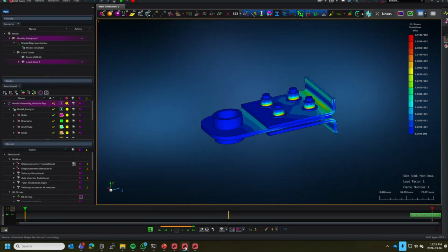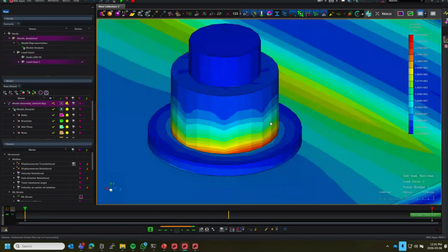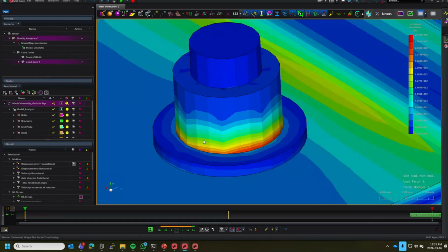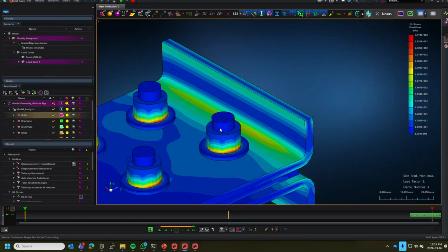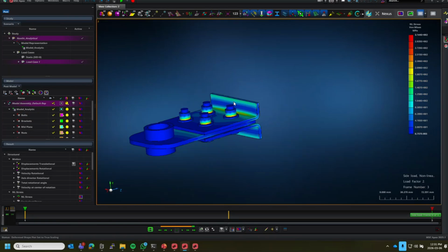If I plot the same with analytical, that's more what I expect to see. Okay, now again, there's these little spikes there, but that's most likely due to the way that I've meshed. It's relatively coarse washers and so on, for argument's sake. Okay, so that then effectively concludes the session on contact. I've covered the parts that I wanted to cover. Are there any questions or comments?